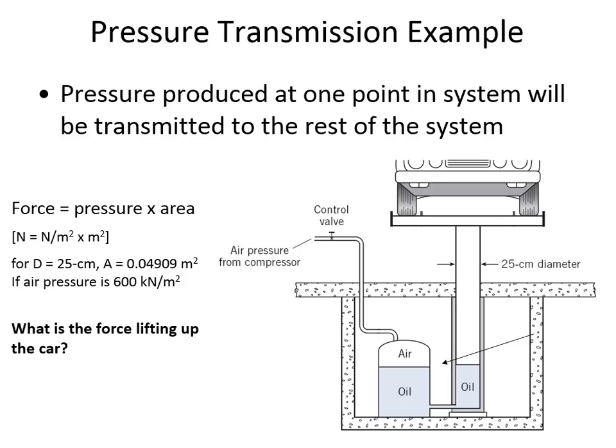You know how I told you that by default, if you have no other information, to just assume that the density of water is 1,000. It's only when I tell you the temperature that you should go look up to find the exact density. Well, by default, when I give you pressures, they are going to be gauge pressures. The exception will be when it needs to be absolute, or when I tell you that it's an absolute pressure. So it'll just be like a gas law problem, or cavitation problem, vapor pressure. Those are the rare instances where pressures will need to be in absolute terms.